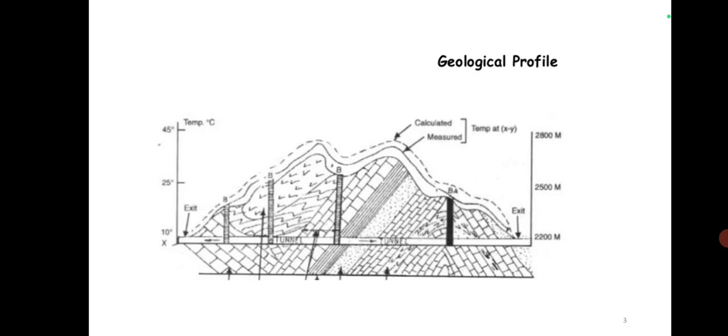So consolidated rocks means we have to use a tunnel boring machine. It is very hard to drill through the strata, but it is stable and it offers a very hard, crystalline structure, so it is highly durable, and it will be safe. Whereas soft rocks means the excavation cost is low, and we can easily drill the rocks, but they are not self-supporting. So you have to provide lining, and all the concrete lining is to be provided. So that actually increases the cost.